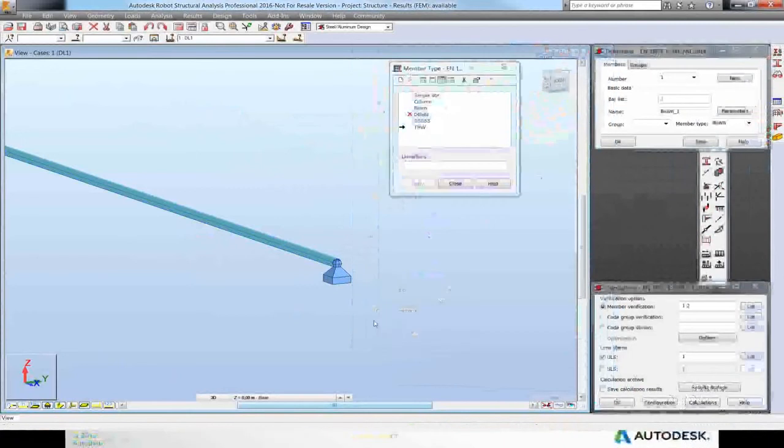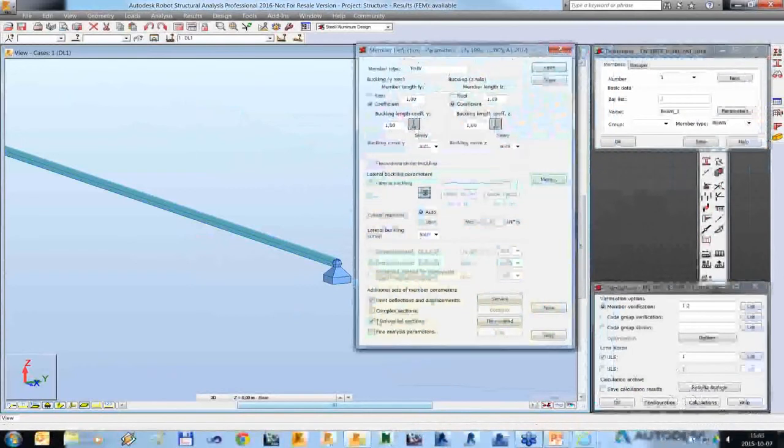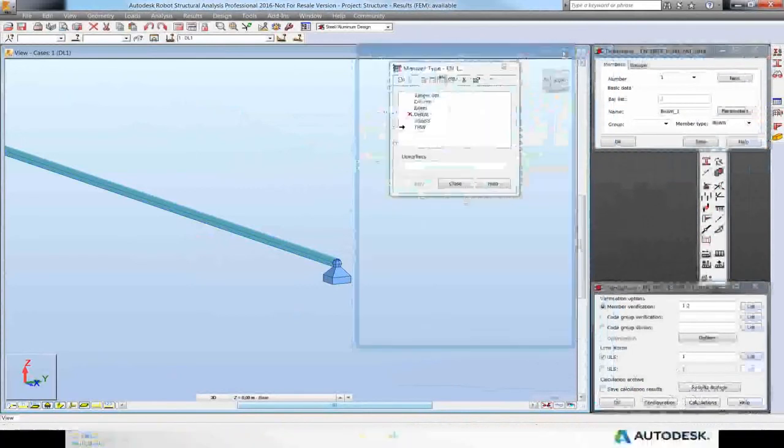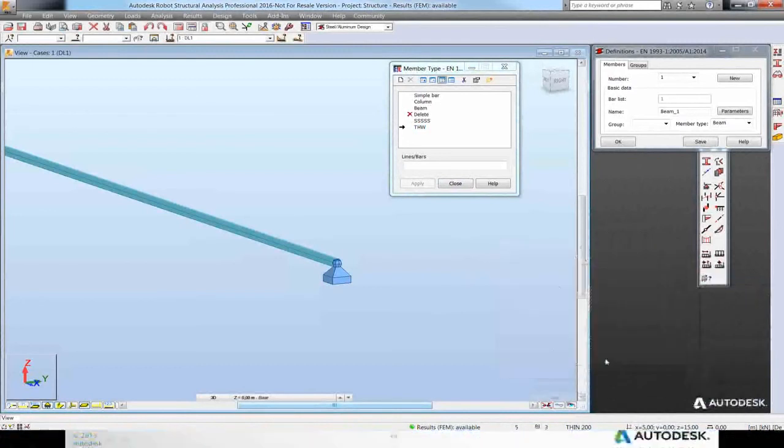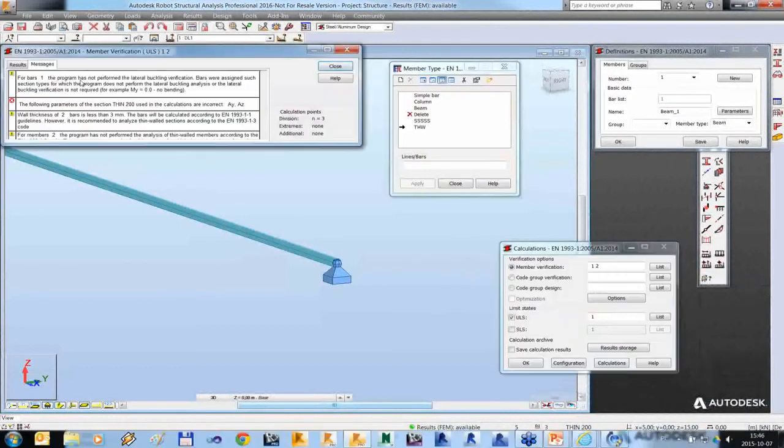After activating the FinVault section check, additional conditions apply: the correct section shape type must be set in the database, and the checkbox, I guess, at the end of the record must be marked. And then the rest of the design is made in the same way as for Robot's standard section database.